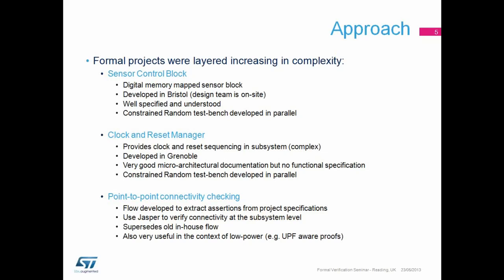We had a lot of really good microarchitectural documentation, lots of schematics. What had happened was that the designer was quite old school. He designed this by schematic and then coded it in Verilog, and effectively gave us a bunch of microarchitectural docs as the functional spec. But it was nowhere written down what the functional response should be, given a functional input. What's actually supposed to happen? And like I said, it's very complex and very timing critical. So again, we developed a constrained random test bench in parallel so we could make comparisons and make sure we didn't miss anything.